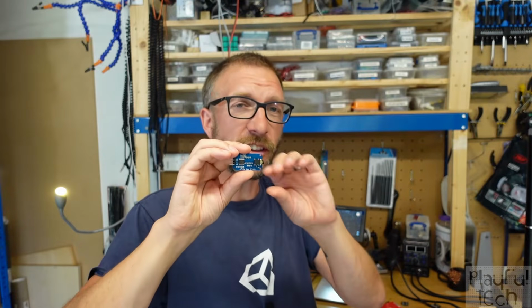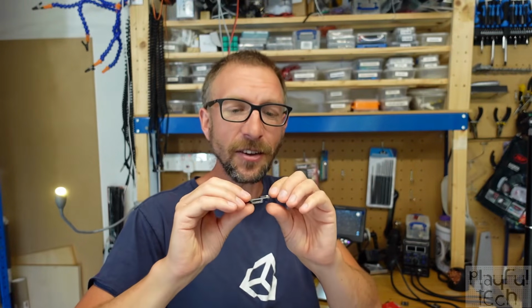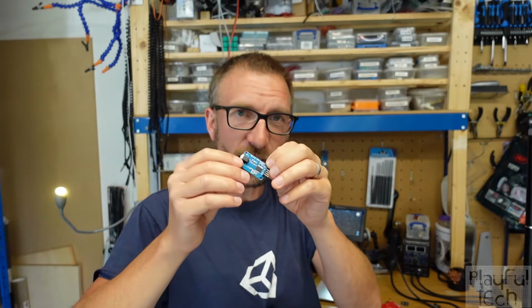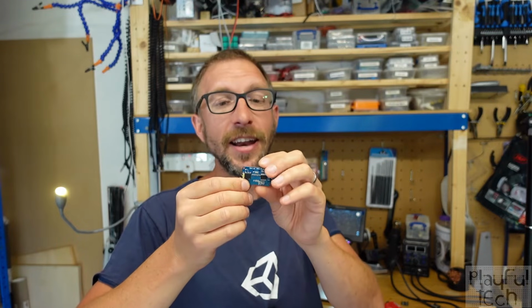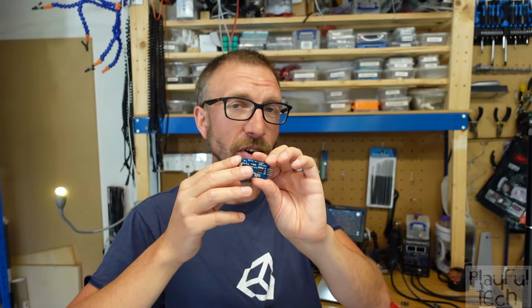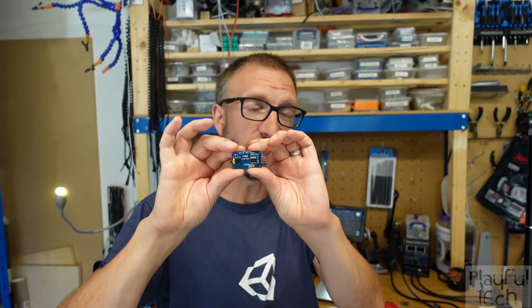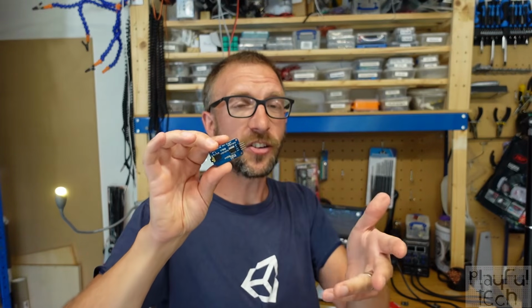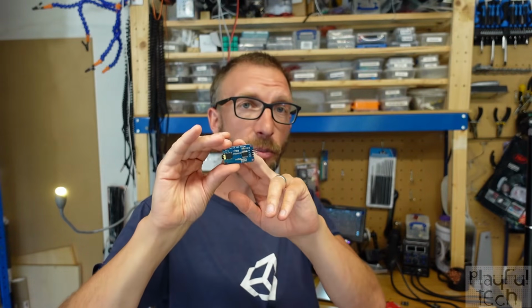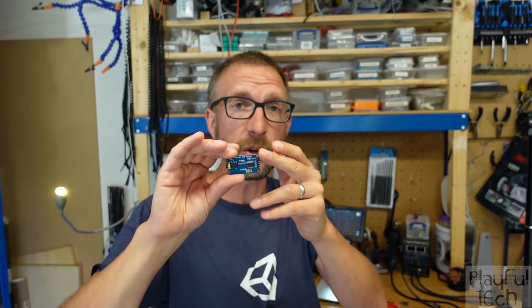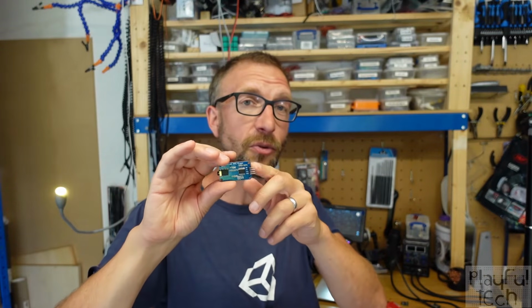It's also a little bit more tolerant and easier to use than the DF Player. It already has a built-in resistor on the receive signal, and it has some capacitors on the power supply lines. So those external components that I said had to be added to the DF Player are already on this board. You can wire this straight up to an Arduino 5-volt power and ground and 2 GPIO pins for the transmit and receive signals, and it will work great.